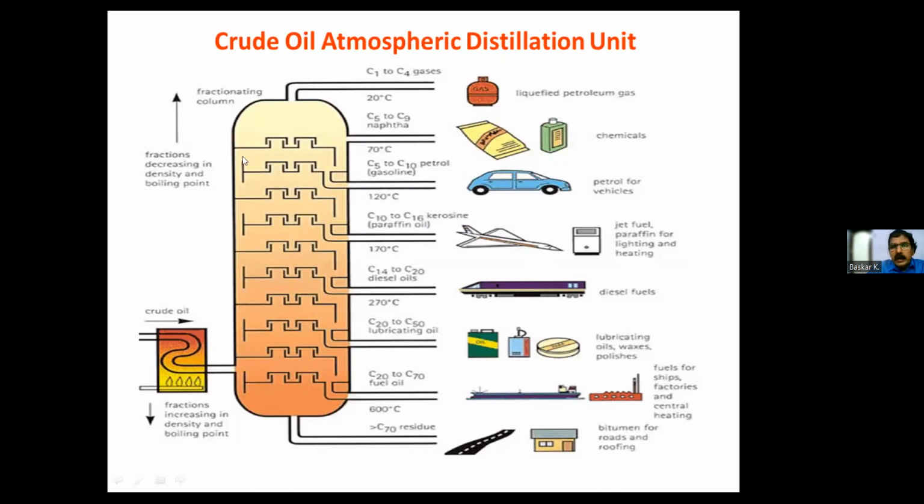This is because this is a very critical unit for the entire refinery. The crude oil is fed into the atmospheric distillation tower, where the pressure is maintained at 2.5 kg. So this is called the atmospheric distillation tower. The feed enters at 470 degrees, and different temperature profiles are maintained to draw products at different temperatures based on the boiling point of each cut. Then these products are withdrawn. These are the products I am talking about. Now, hope you understand. If you have any questions, we can clarify them later. So now we'll move on to the next slide.